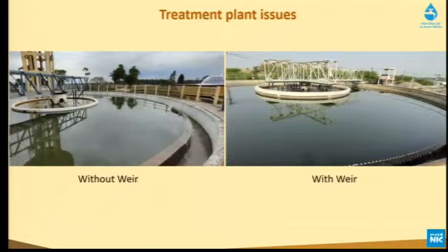The other example I found during the site visit is that you can see the treatment plant doesn't have the weir. So definitely when you design the system, make sure that the proper design is done. It helps in controlling the flow, and it helps in proper sedimentation. Unless it is properly designed, the system is not going to work in an efficient way.